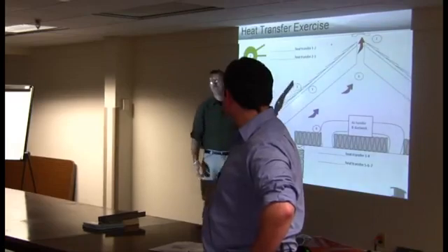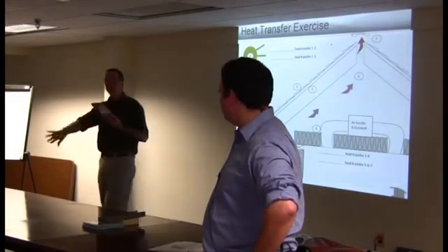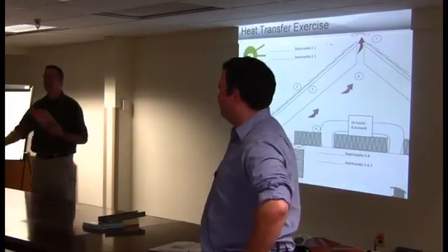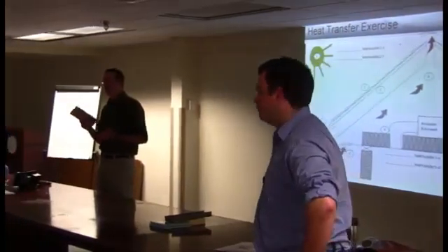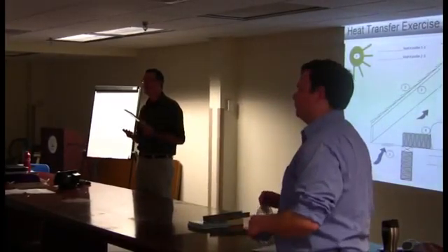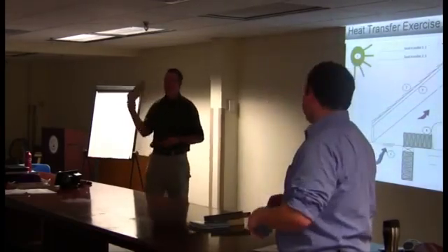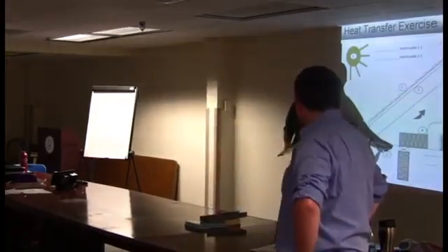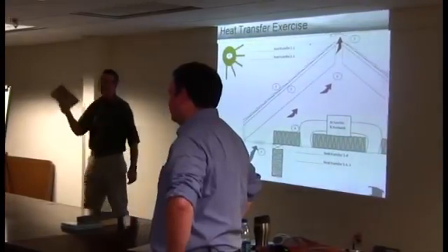That's okay. But the whole thing about this surface is that it just doesn't give away its heat, and it basically slows down the overall entry of heat into the attic assembly. It doesn't really have much effect on the shingle life because the shingles are really being cooked by something else, right? Not the decking. What's cooking the shingles? The sun, right? So in terms of commercial buildings, if you're going to do a vented assembly like you see here, then I think this is a very good product, especially the further south you go. This is a really good idea.